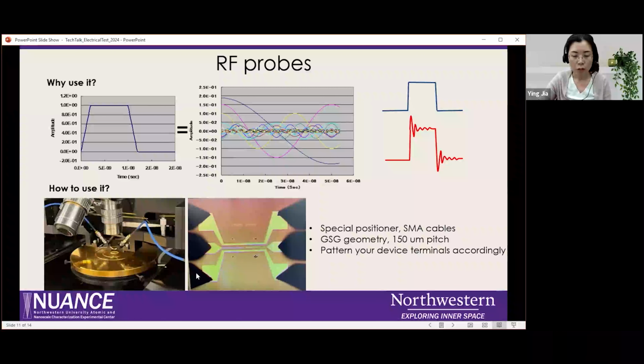Each probe has 3 pins, and the 3 pins will all touch onto your device. This is a device that we get from a resistive memory device, which you can basically consider like a resistor. So the resistor is over here, and all around is the shielding. For these probes, we have 3 pins. The middle 2 are passing the signals: one applies voltage, another measures current, and the outer 2 are for the shielding.